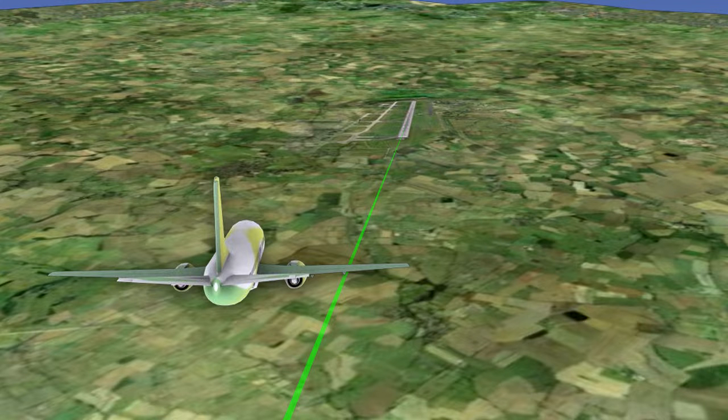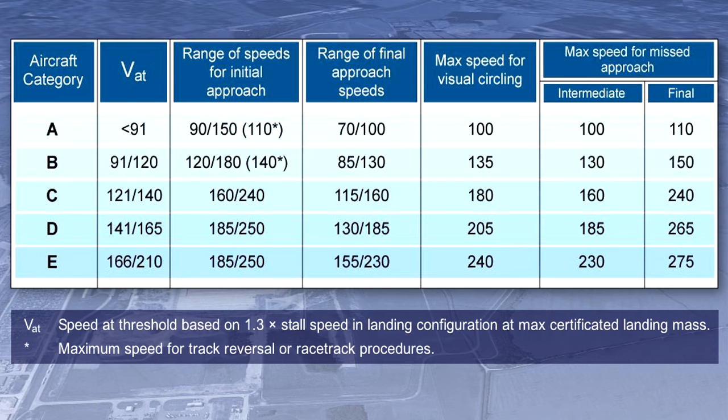All procedures depict tracks, and all pilots must attempt to maintain the required track by flying accurately and applying corrections for known wind. Whilst flying an ILS precision approach, pilots are expected to be able to fly the aeroplane during the final approach phase with a track accuracy equal to no worse than half full-scale deflection of the ILS indicator needle. Aeroplane performance has a direct effect on the airspace and visibility needed to perform the various manoeuvres associated with the conduct of instrument approach procedures.